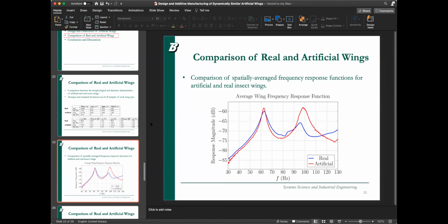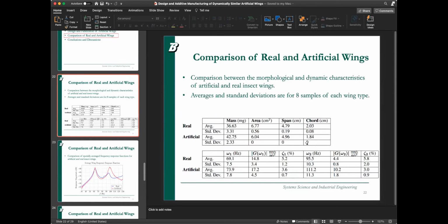Yeah. So first of all, some previously developed the process using carbon fibers. They manually put those carbon fibers into the molds, into the laser cut or photolithography. So it is manual work. It will have a large variation, so you cannot ensure that from the first one to the second one they are identical. Basically, 3D printing can be automatically produced, right? So this is one advantage. And second, you can see from the morphological summary, we have almost zero variance. But if manually put, you cannot have this.